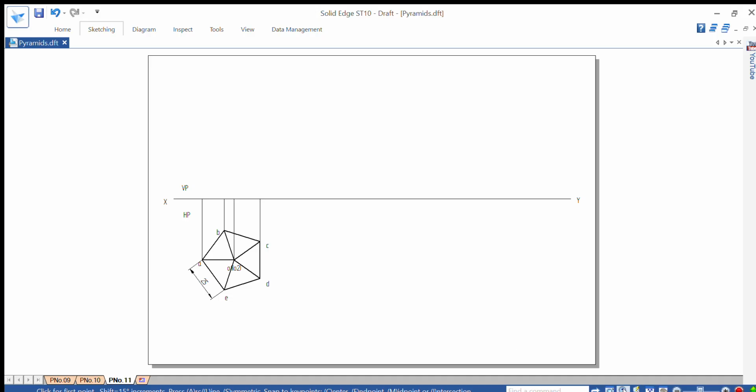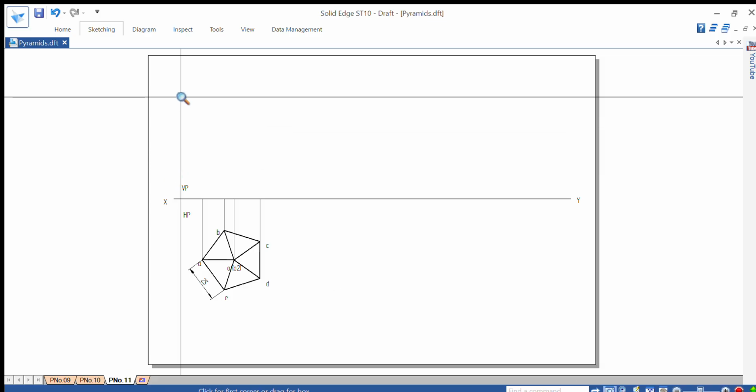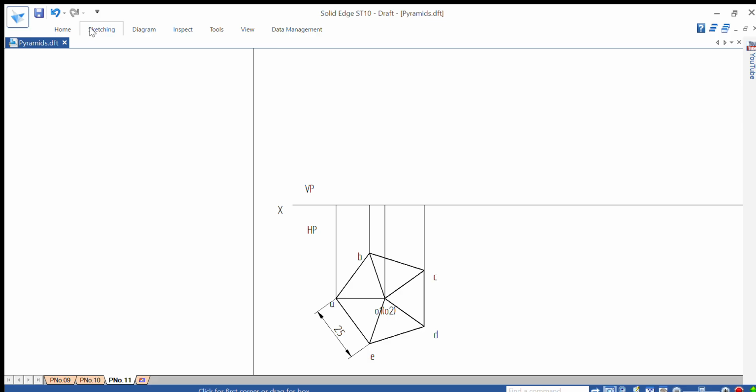Okay, only zoom this much area. Go to line, select the axis line type, medium thick 0.35, from axis line. Type 60 mm length, angle is 90. Line type is axis type. From this point, length of the line is 60, then angle is 90.